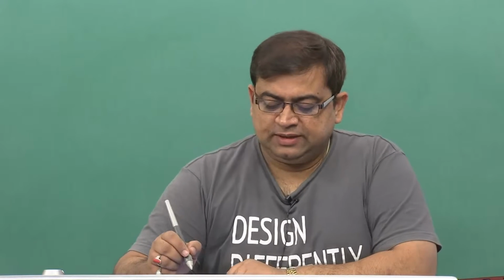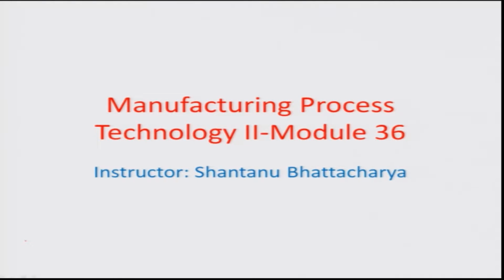Hello and welcome to this manufacturing process technology part 2 module 36. We were talking about EBM machining and we were also talking about a numerical estimation through the Buckingham pi theorem of the beam matter interaction, which would lead us to at least the governing power law with which we can relate the various parameters related to the process.